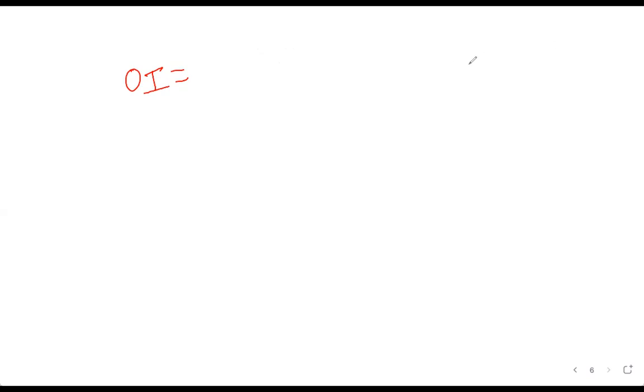Your query vector is in an FPGA register. You keep streaming the rows of the matrix. This is your n by f matrix. You first stream the first row, and then the second row. You keep streaming the rows, and you keep computing the dot product with the query vector.